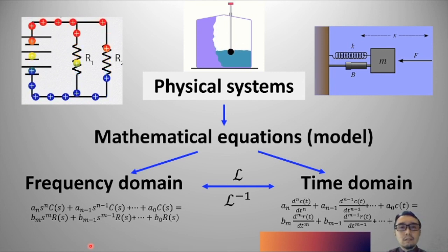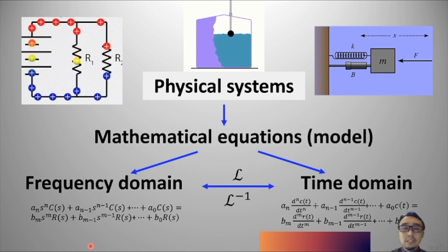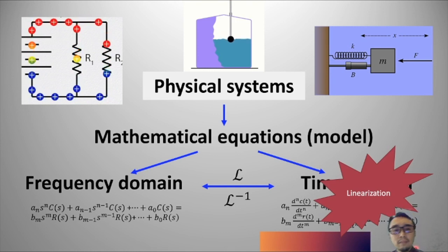I think you have spent a lot of time trying to obtain the mathematical model of real physical systems. You should have looked at electrical, mechanical, electromechanical systems, and maybe water level systems, and trying to obtain the mathematical representations. And normally you will start with obtaining the differential equations in the time domain, and then transforming that equation using Laplace transform into the frequency domain or Laplace domain, as shown here. Although in some cases in the time domain equations you would have linearity or non-linearity present in some physical systems. So the non-linearity can be linearized first, and then you can apply the Laplace transform to obtain the equations in the frequency domain.